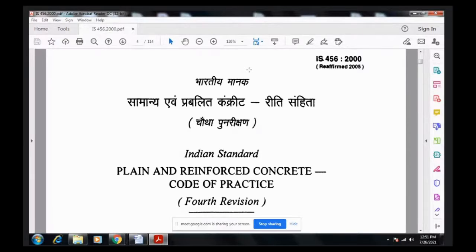So that is why you have to understand that after getting the bending moment, shear force, axial force, all these things, after doing the structural analysis, then how to decide the sectional dimension. You will take inside it stirrups, and the spacing of those stirrups, diameter of the stirrups, diameter of the longitudinal bars, and the detailing.